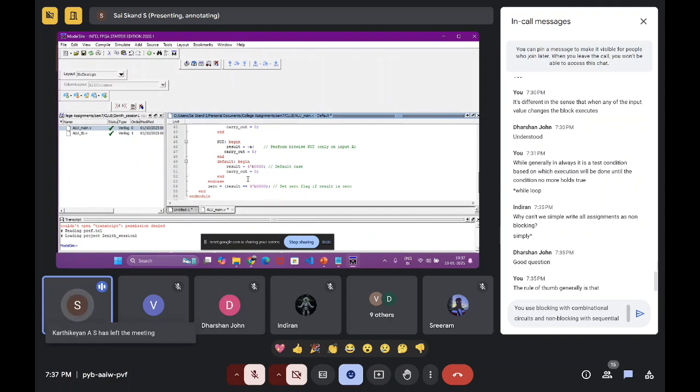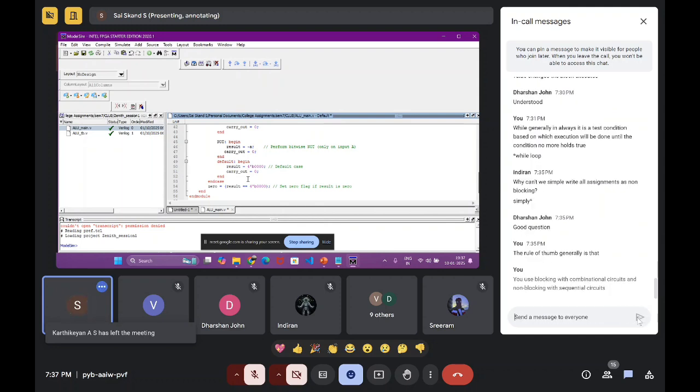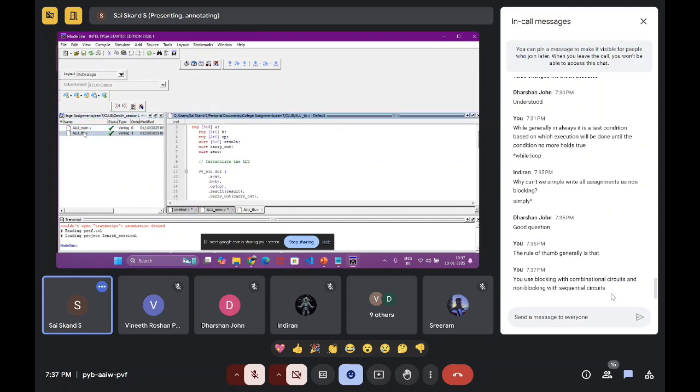Basically it's for testing this block. For any design, we are going to perform a test. That is the test bench. We are going to use the same Verilog. Okay, I need to open it. This is the test bench. We are naming it ALU TB, test bench, though any name would work. So this is the syntax for that.